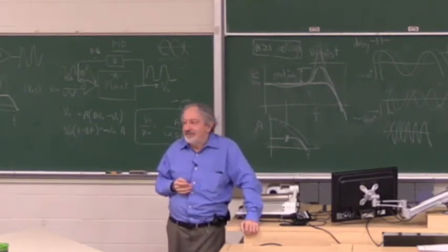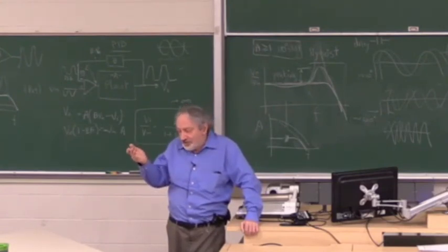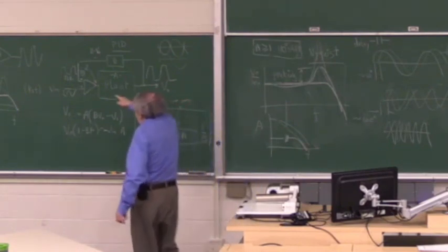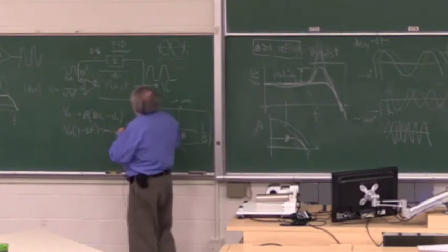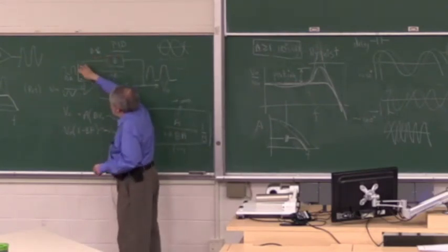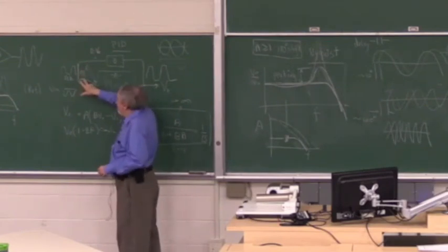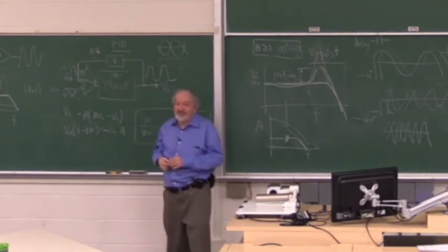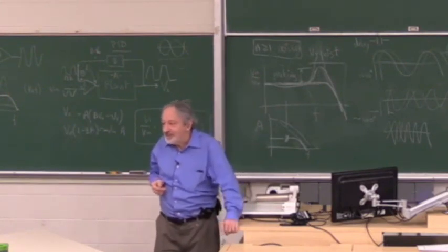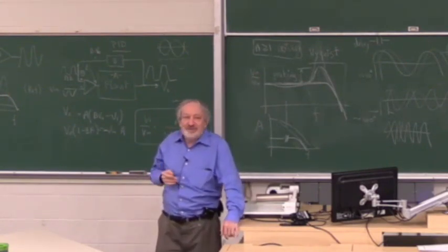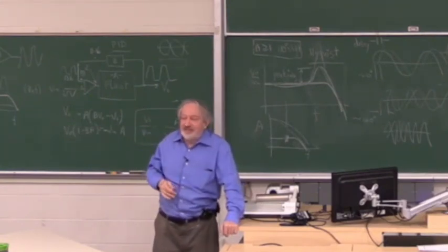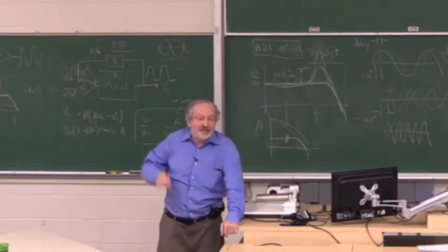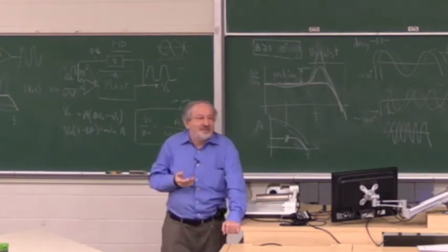Because your feedback also goes way up. Yes, the signal goes up, the feedback is constant, but the error signal is big, and this is supposed to cancel it, right? Let's say at the resonance frequency this goes up, but this is supposed to bring you back a big error signal, and the big error signal should suppress the resonance. But it's not instantaneous. You're getting closer, but because that's what a servo does. If there's an error, it suppresses it. If there's a big error, there's a big current trying to suppress it. But you try it, it doesn't work.